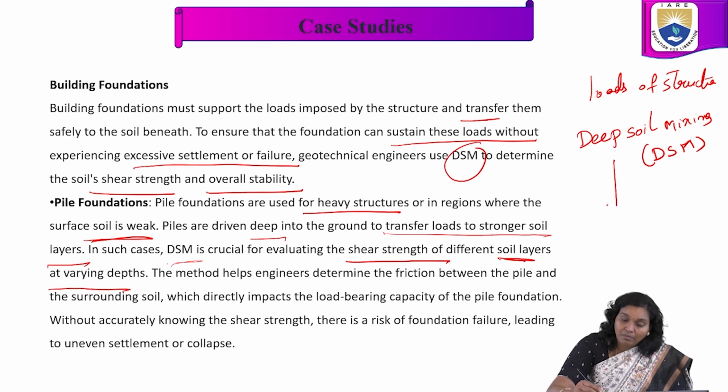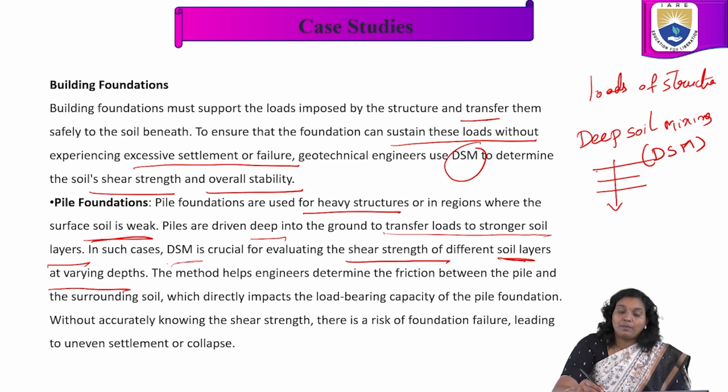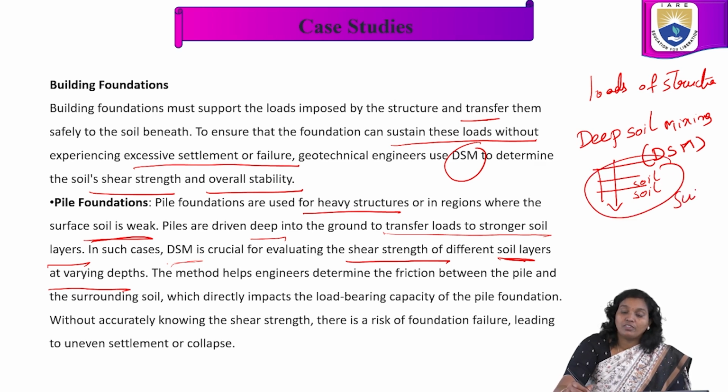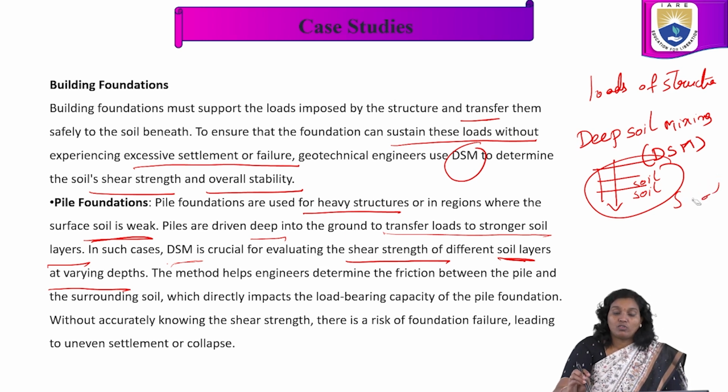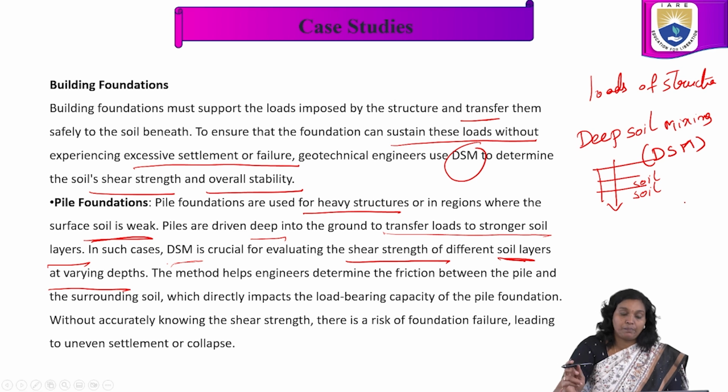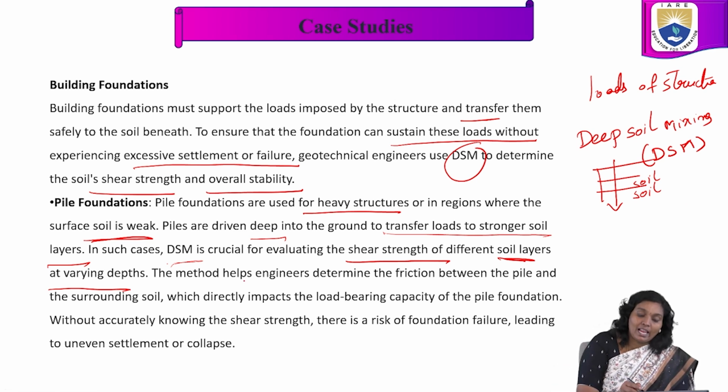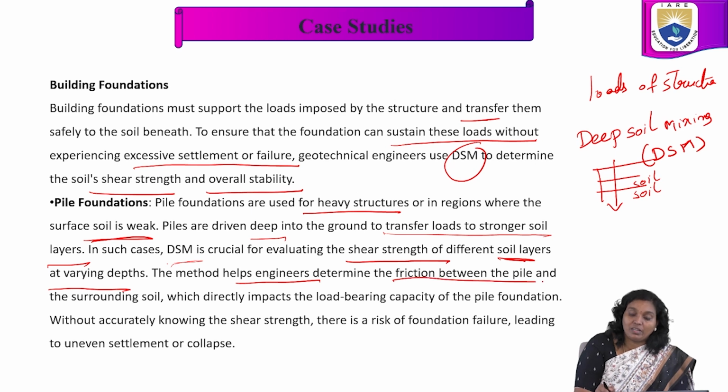Here also we may observe different depths having different types of soil conditions, each with their own kinds of surroundings. These are all the parameters we have to understand once we choose deep soil mixing as a ground improvement technique. This method helps engineers to determine the friction between the pile and the surrounding soil, which directly impacts the load bearing capacity of